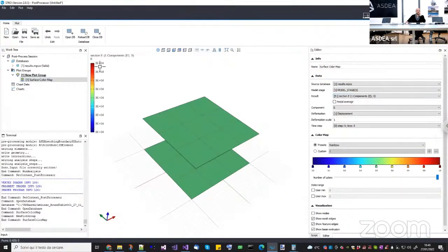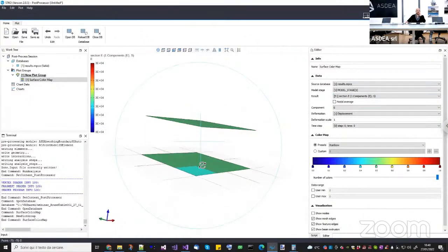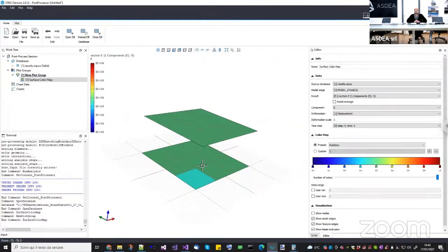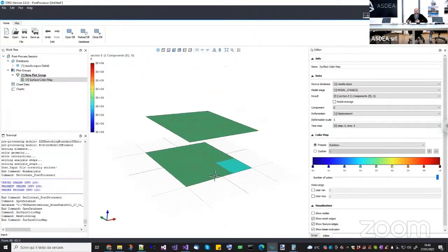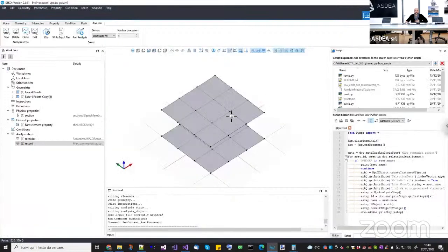Okay, so we have 3 to the power of 4 in both slabs, which is exactly the initial Young modulus that we wanted. Okay. Now the point is, how do I change this one in TCL? Well, in OpenSees, you can use the concept of parameters to update these values. Okay, so let's go back to the preprocessor.